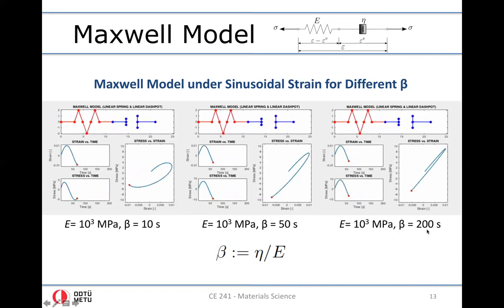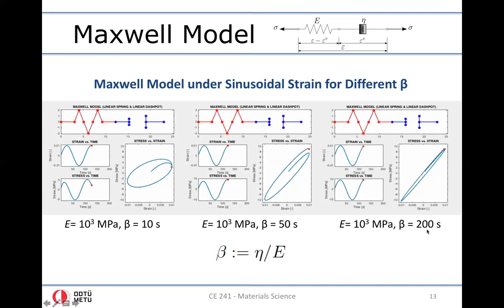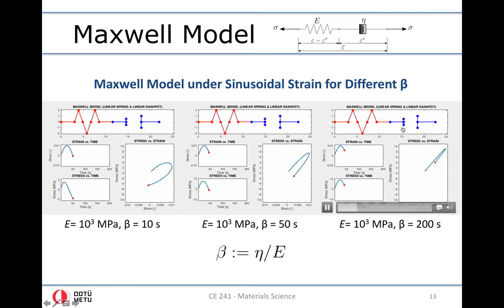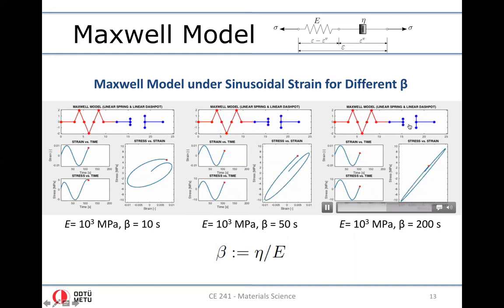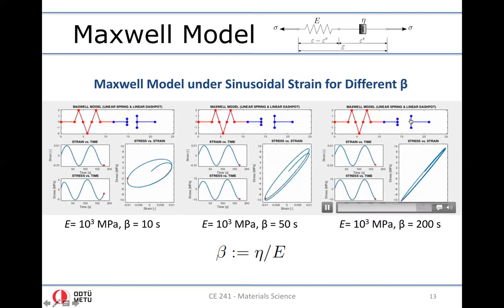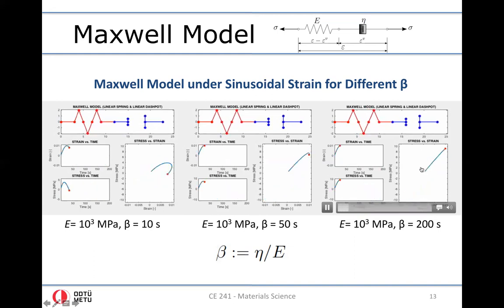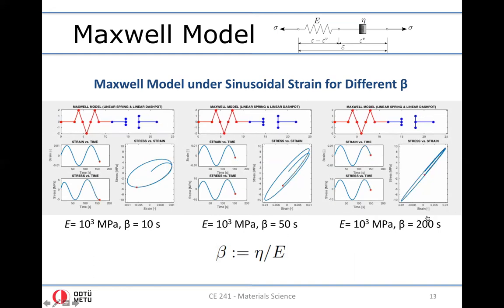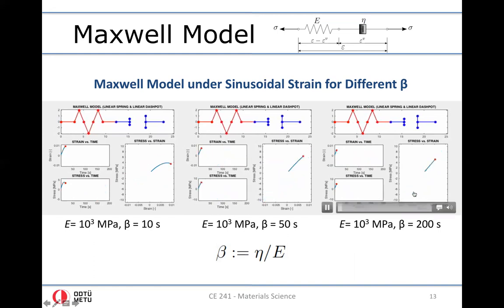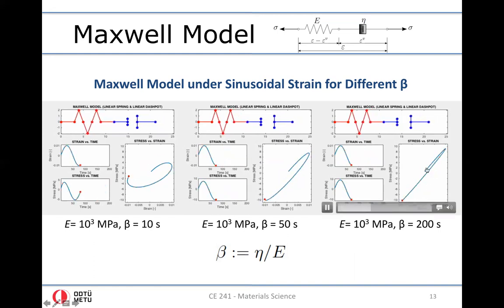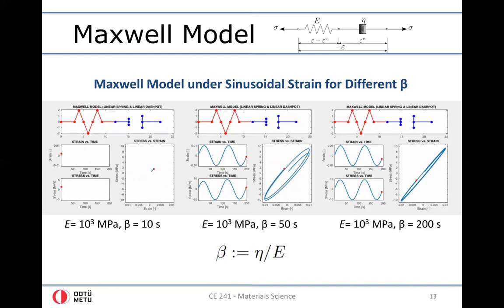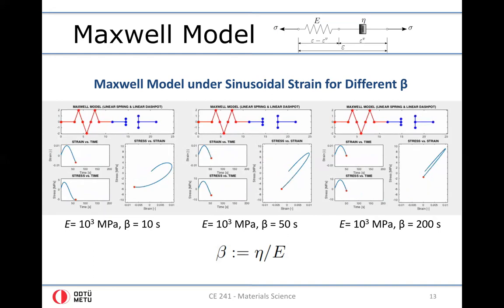When relaxation time goes to infinity, in other words, when we fill the piston with an extremely viscous material, as we can imagine, this curve will converge to the linear elastic response, right? So you will be going forward and backward on the same curve without generating any hysteresis, in other words, without dissipating any energy.